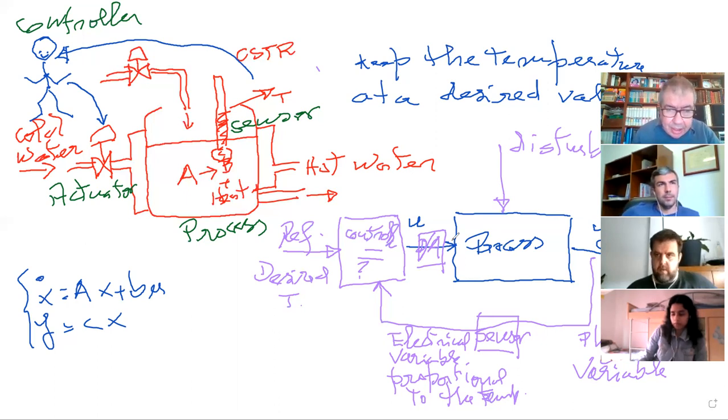Okay, and to receive the data, the sensor outputs some electrical tension. So you have here the inverse, which is an AD converter. It converts an electrical tension to a digital number connected to the input port of the computer. Think of a port of the computer as a position of memory.